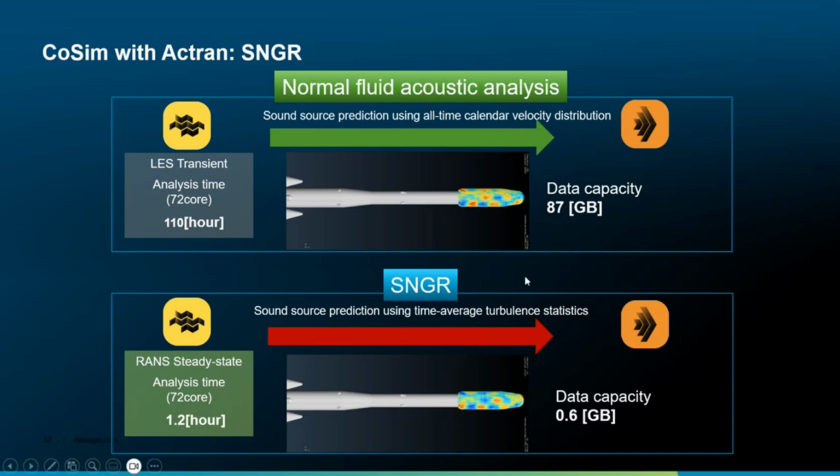We have been able to develop another approach in which, of course, we won't get all the results that we can expect from the traditional approach, but it's enough to make some iteration exploring, let's say. So we can use just a light CFD simulation. If you compare the calculation time here, you can see what I'm talking about. Again, pragmatism. You make a light CFD simulation, you use it as boundary condition to get a very simple acoustic simulation, giving you the result you were looking for.